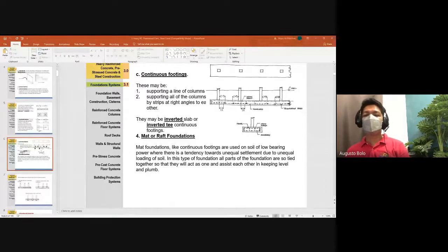1.2 by 1.2 footing is enough. For a 1-story, 1 by 1 is also fine. It can even be less than 1 if the condition of your soil is okay and your structure is small, it's also fine. Did I answer your question, Rose?